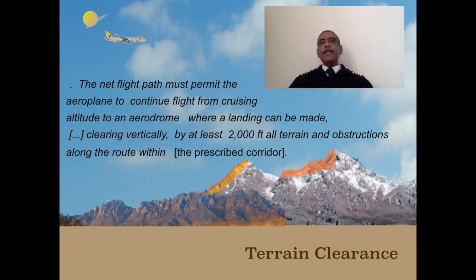And in this, if there is a very small segment where the 2000 feet rule cannot be met, a small detour in the route can be planned, and as long as the regulatory authorities are satisfied, then they would accept a small deviation in the route and getting back to the route once the particular obstruction is cleared. So that's what is the difference between the 1000 and 2000 feet rule.